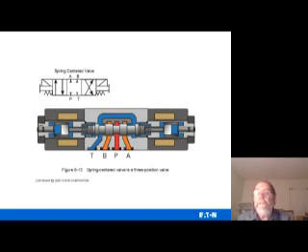And here's another one. This was shown with two solenoids to move either left or right, and it also has two springs. So if neither one of these solenoids are energized, the springs will center to where this one is here. All ports are blocked off. It's a four-way, three-position directional control valve.